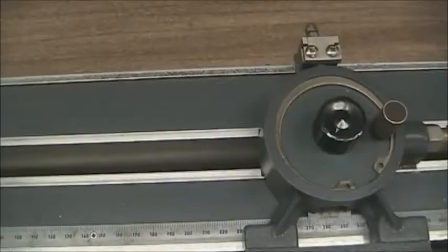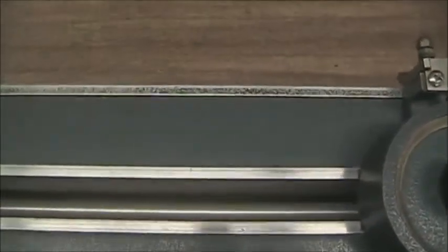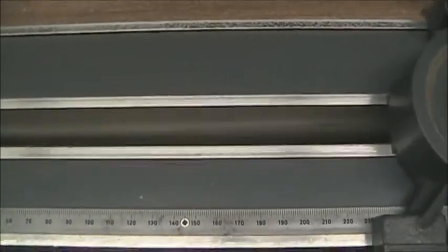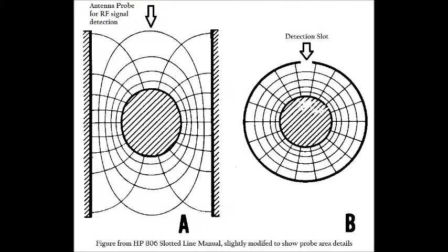I'm going to turn it on the side. You can see the center conductor down in that channel. This is about 3/4 of an inch, it looks like there in that slot. That is the center conductor down in there. This is a special form of transmission line we call a slab line because it has 2 ground planes on either side and then the center conductor.